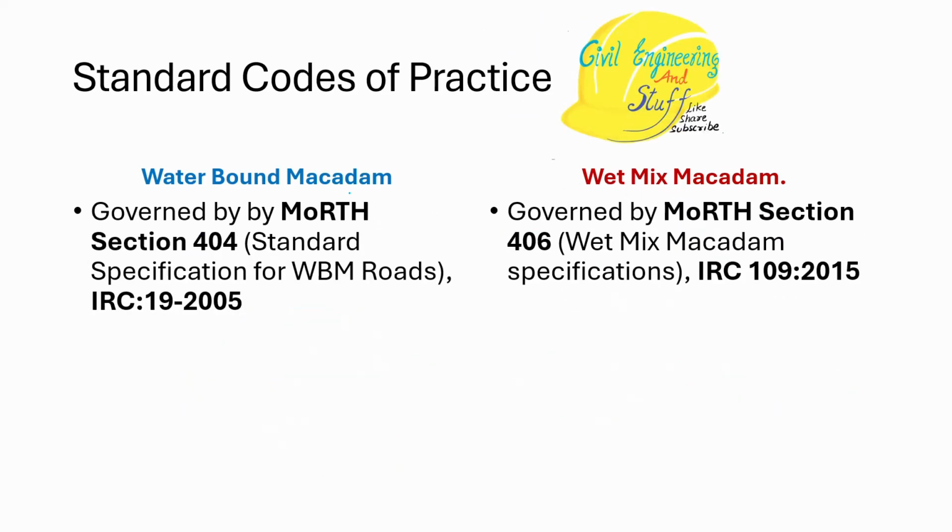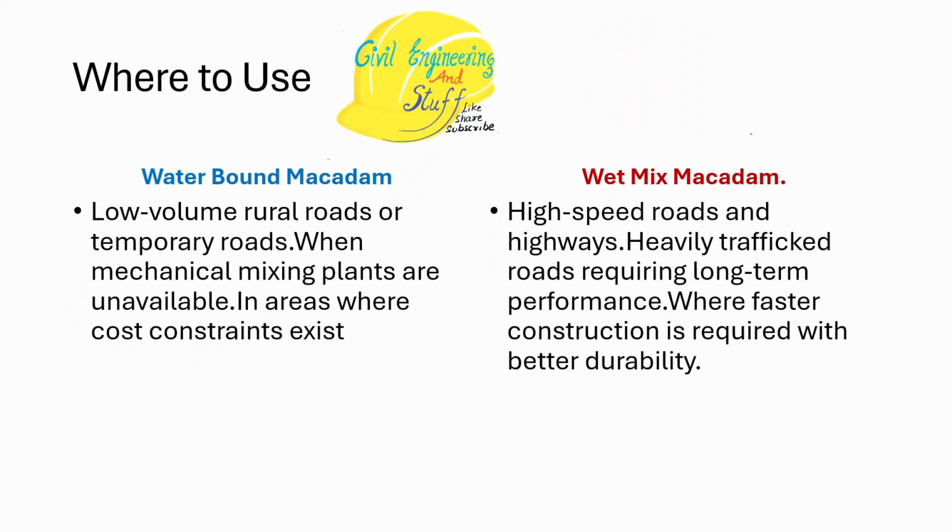Which code is used for WBM? If you're referring to the MoRTH specifications, we have section 404, and IRC 19 is referred for WBM, while for wet mix macadam, MoRTH section 406 is referred, and IRC 109 2015 is used for wet mix macadam. Now, where do we use these WBM and WMM mixes?